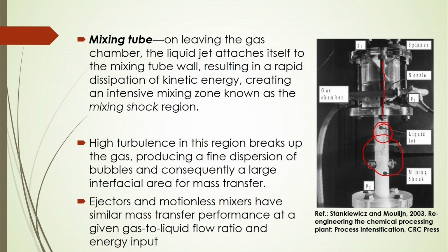You will see that bubbles will be there in the mixing zone in the tube, and this mixing zone will give you intense mixing of the phases of gas bubbles and the liquid, due to the high kinetic energy dissipation supplied by the kinetic energy of the liquid jet. This intense mixing zone may be referred to as the mixing shock region.